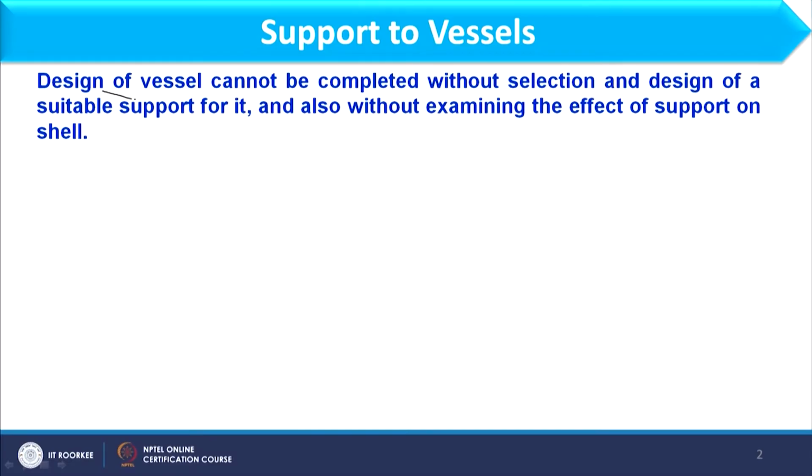Actually, whenever I am designing a pressure vessel, I cannot leave the pressure vessel as it is. It requires some structure or some assembly so that it can be connected to the foundation, and that assembly is basically called a support. So, design of vessel cannot be completed without selection and design of suitable support for it, and also without examining the effect of support on the shell.